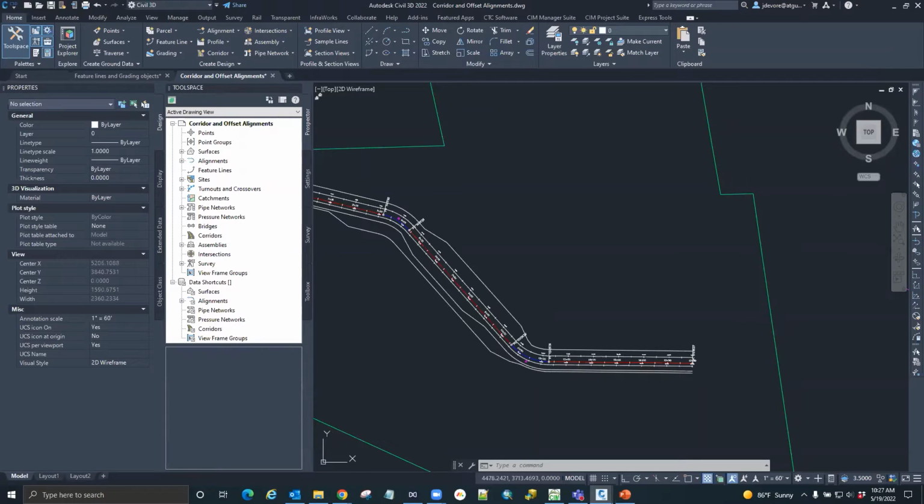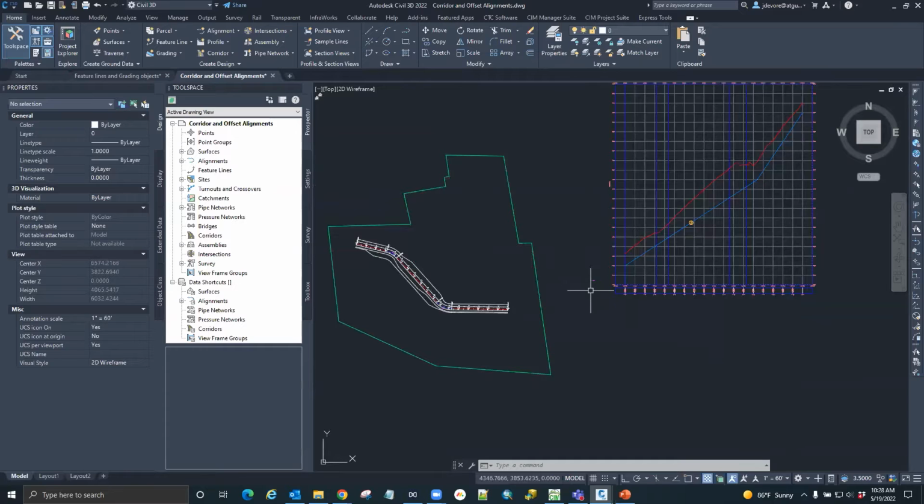And it's a cool workflow, because then as you make changes to, let's say, street A, that offset alignment is connected to the connected alignment, which means your return will update automatically. It's an interesting workflow. It's something I don't think a lot of people use, but it's a very powerful tool to keep your intersections dynamic. Yeah, and before the intersection tool came out, that was how we had to figure that out, because the corridors were just perpendicular. So we had to create different assemblies for those returns, which you do in the intersection tool anyway, right? But yeah, so it's just keeping it in there.